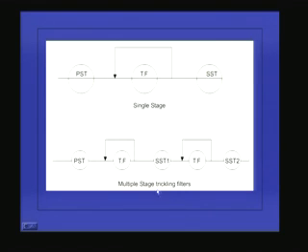And this is a multiple stage trickling filter: primary sedimentation tank, and this is the trickling filter. Recirculation, this recirculation can be either from here or we can have the recirculation like this, and this is the second trickling filter and recirculation, and this is the secondary sedimentation tank.